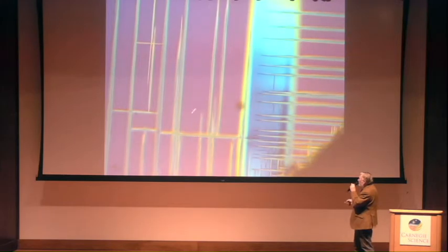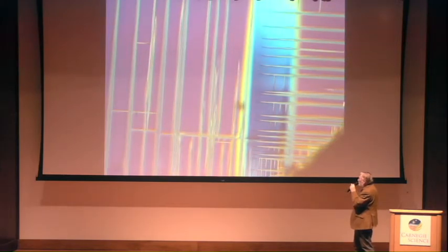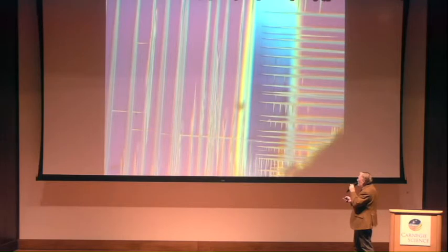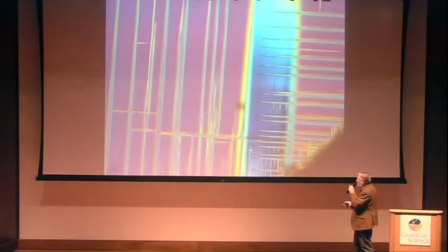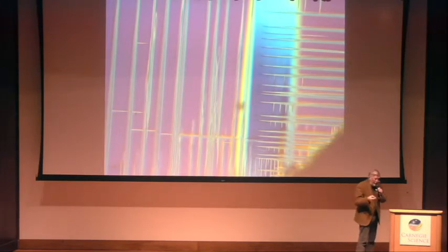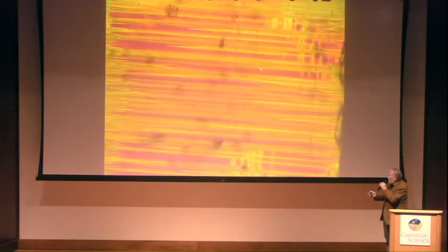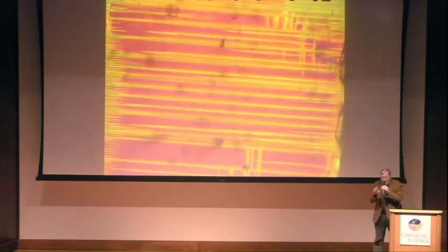Now here is the ferroelastic part, so I squeeze a crystal, I get my primary domain walls or domains, the secondary domains, vertical, then the tertiary ones, and so forth. And if I carry on with that, I go almost to a glass state. And if I rotate the crystal by a little bit, then you can see it's the same crystal as lanthanum aluminium oxide. You can see that this behavior now is very angular dependent, so I can actually, in an engineering fashion, make patterns which are characteristic for what I need to do.